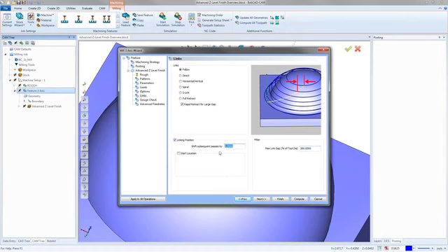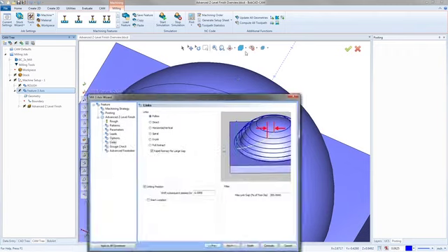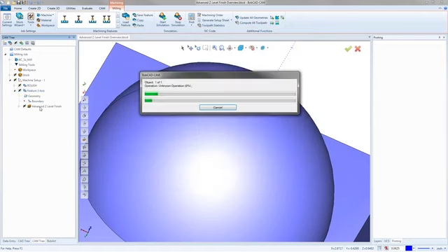So the shift changes it. Normally, if you leave it at 0, you're going to get the finish like we have. Starting from the center, it goes at one point, straight down all the way. So what we're allowed to do now is shift any subsequent passes. If I say shift them all, shift each start by 1/8 inch, and I hit compute, we're going to see after this calculates, the links are going to be a lot different.